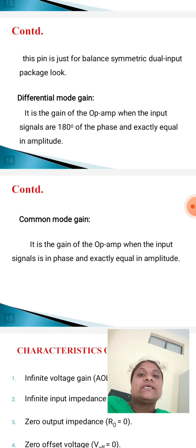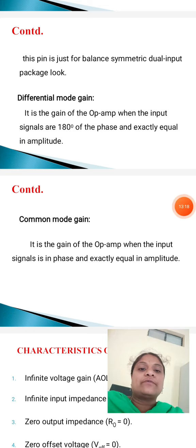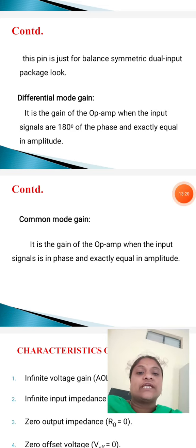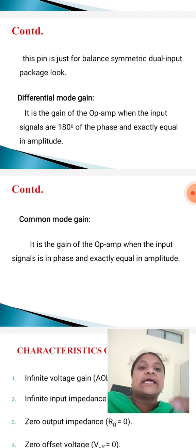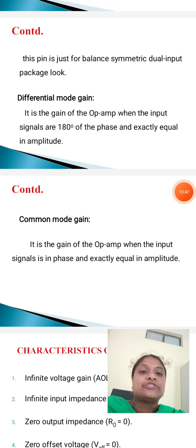Now, differential mode gain and common mode gain. What is the differential mode gain? It is the gain of the op-amp when the input signals are 180 degrees out of phase and exactly equal in amplitude.